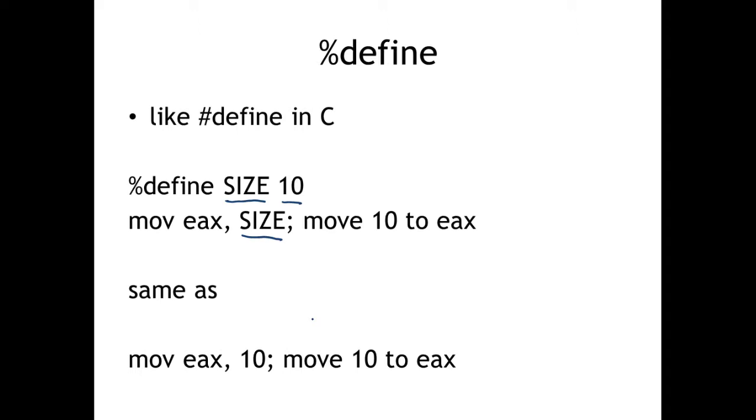And so if that changes, let's say that you define some hard-coded value of 10, and you're using it to control your program, and you use that in 15 locations. If for some reason you have to change that, now it's a 12 or a 15, you can just change it right here, and it'll trickle throughout your code when it's assembled. The alternative is to go through and manually change that yourself, which tends to be error prone. You tend to miss a spot to make that update, which makes your code not work the way you expect it, and adds debugging. And so defines can be pretty helpful. Use those if you like.